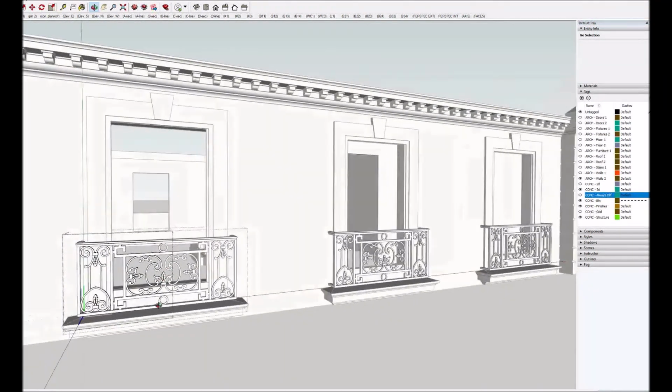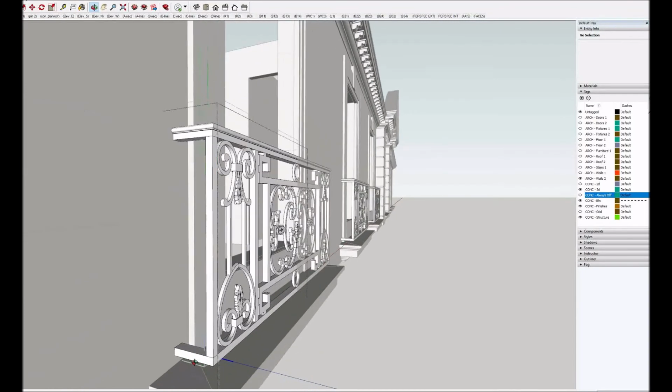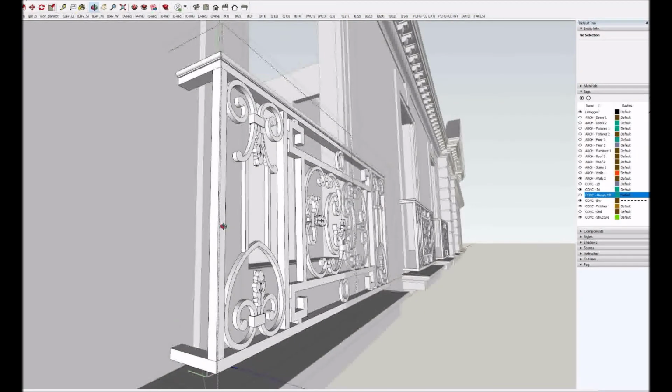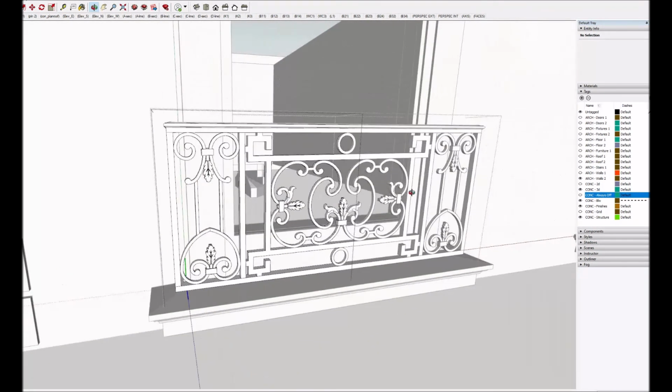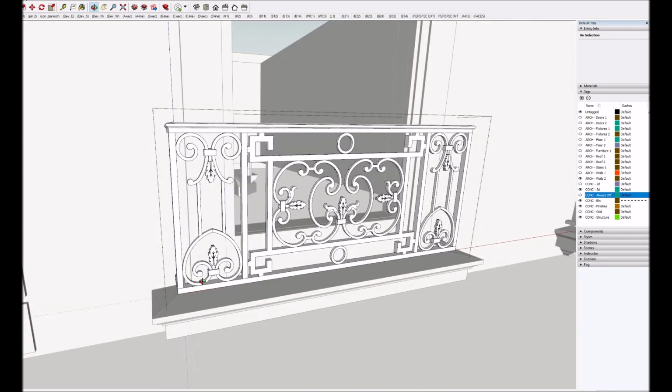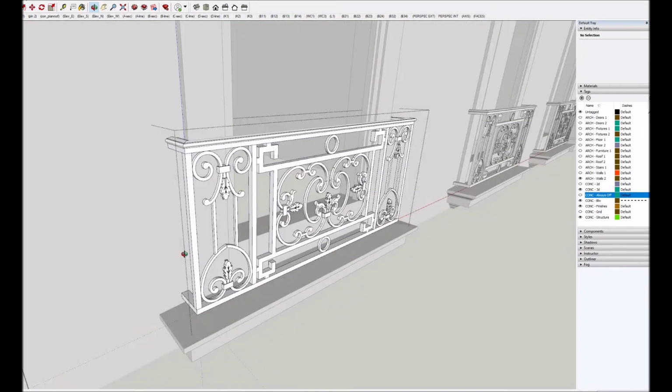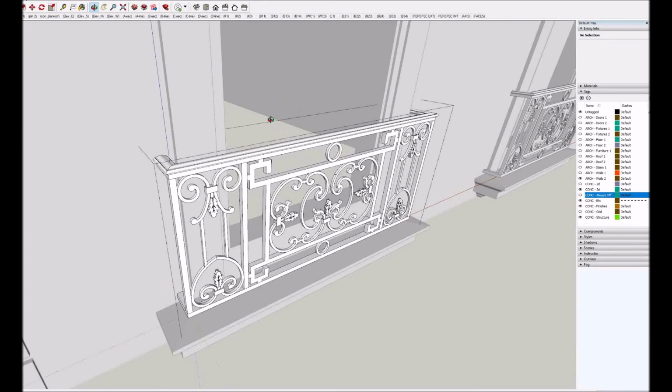Now I made a fairly stout bottom rail, actually a very stout bottom rail and top rail. These are 1 inch by 1.5 inch. Let me check. Yeah, 1 inch by 1.5 inch solid rectangular steel shapes. And then I've got 4 of the verticals that are continuous as well. So I believe that that framework is strong enough to provide the necessary support for anybody who might fall against it from inside.